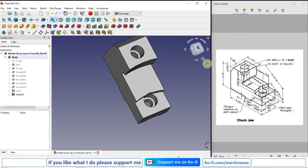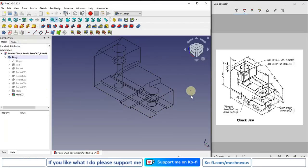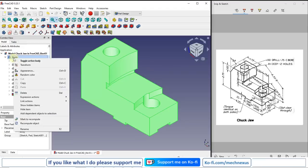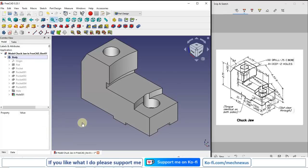We will switch to the isometric and let's see. We will go to the wireframe. If we go in a wireframe, we can see that our hole looks the same here and here, here and here. So this is how we have made this model. And if you want to give some color, then you go to the appearances and I can give it some shiny color like chrome, and I will say close.